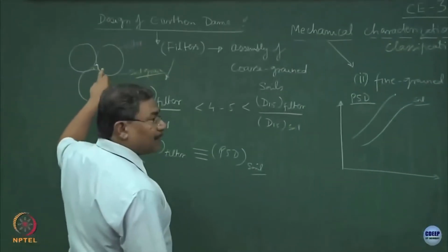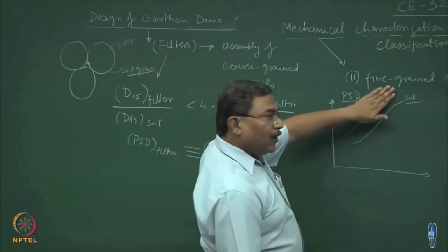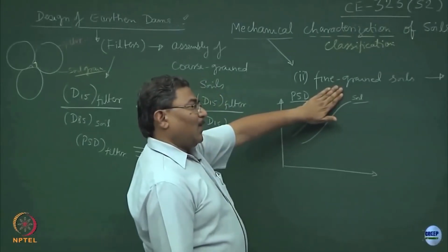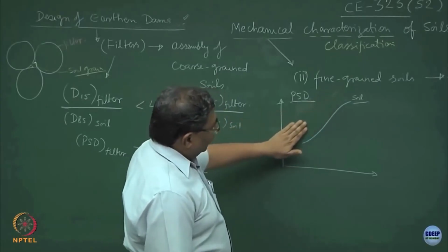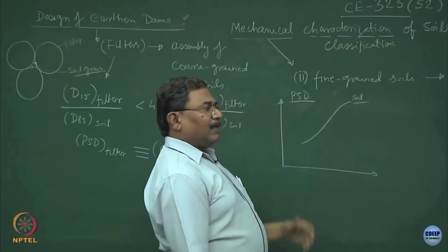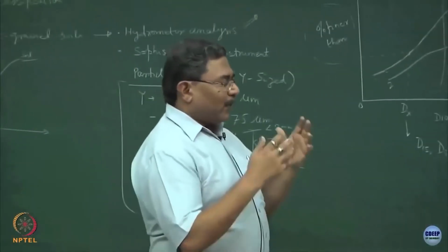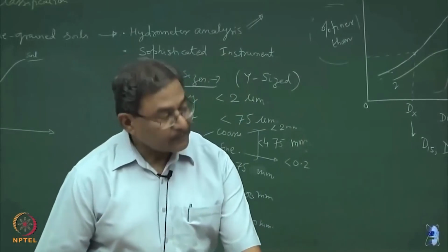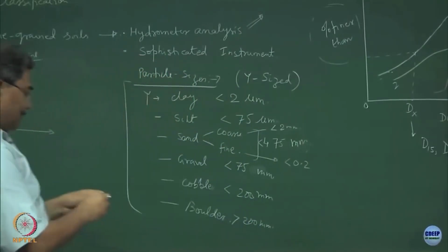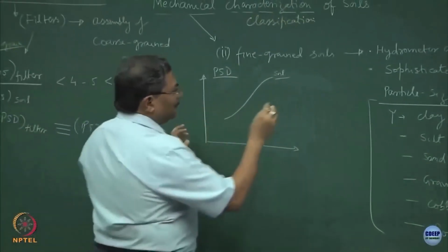The soil particles have to be finer than the filter media. So, this answer is wrong. Why? There is no fun in providing a filter media which is finer than soils. Agreed? Because soils have to be protected. So, this is what we have learned today. Correct? It is interesting. Apply logic. Believe me, you need not mug up anything.